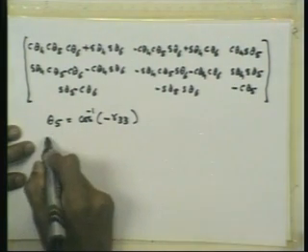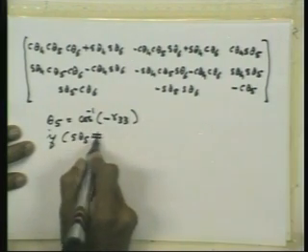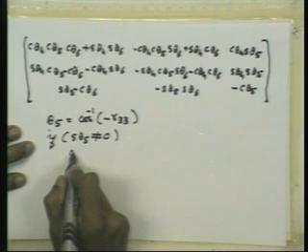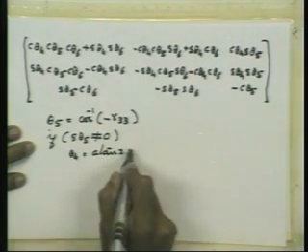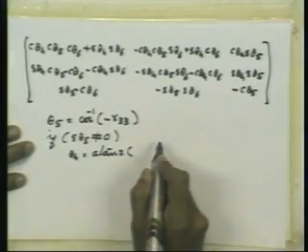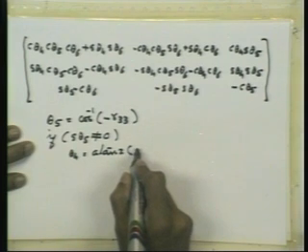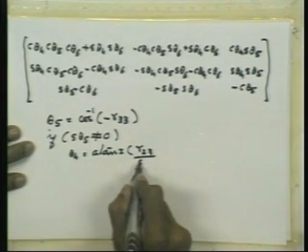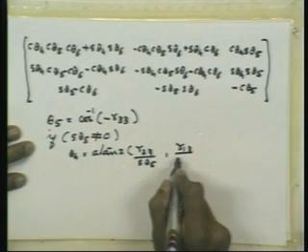So if sin theta 5 is non-zero, then we can very easily calculate theta 4 using this. This is a tan 2 of R23 divided by sin theta 5 and R13 divided by sin theta 5.